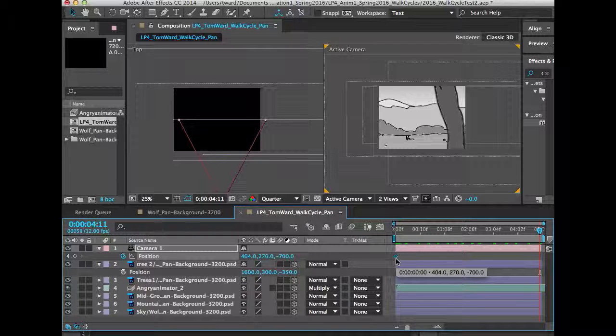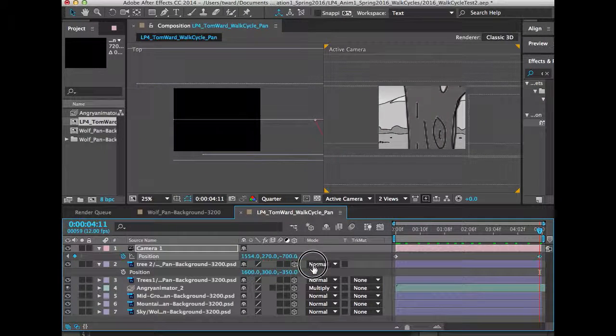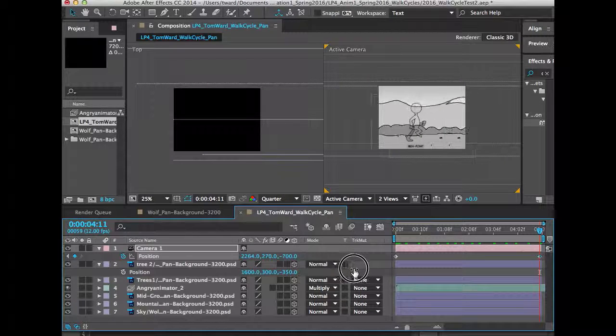So now as I move the X position of the camera, I want my camera to just move along the X axis. It's going to move along to the right to find my character again. I'm going to scrub it along the X axis here, holding the shift key. And I'm going to move it, move it, move it, till I find my character again and I line them up here. So I have them right there, kind of where he was where I started, about the same point in the frame.